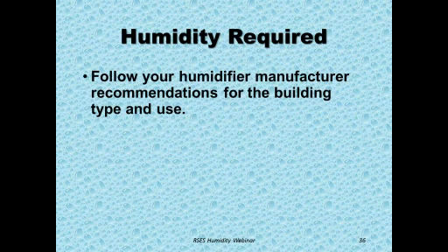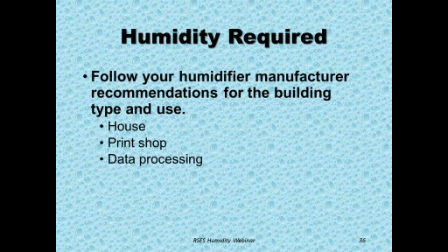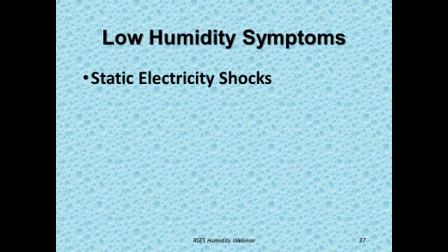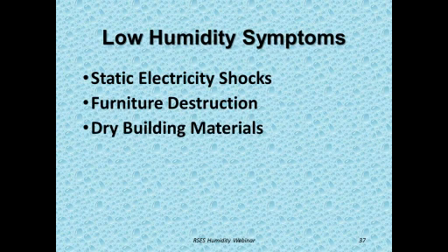Humidity that's required, you should follow your humidifier manufacturer's recommendations for the building type and use. You're going to have house requirements, print shop requirements, data processing, offices, and the list goes on and on. A print shop may require a lot higher humidity than offices.